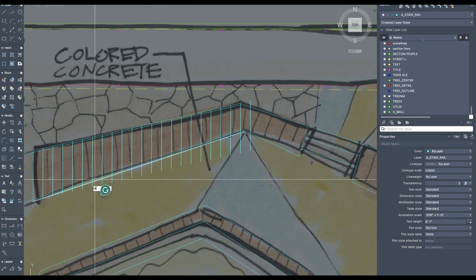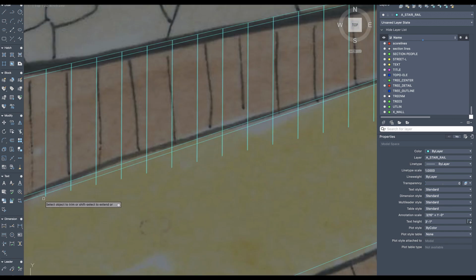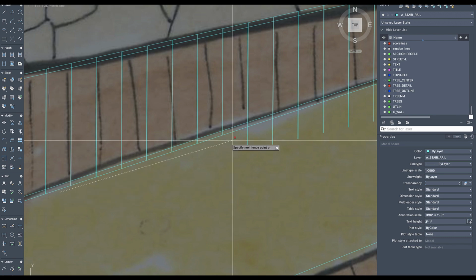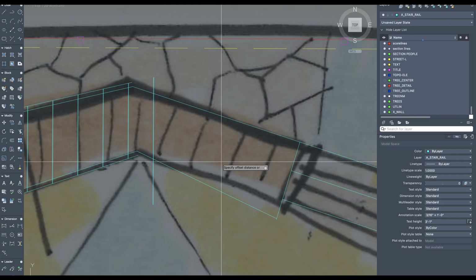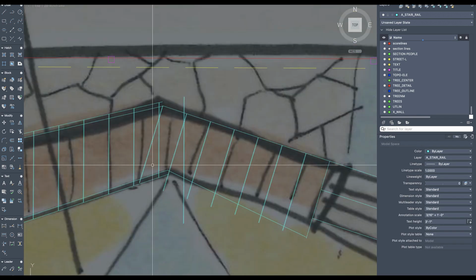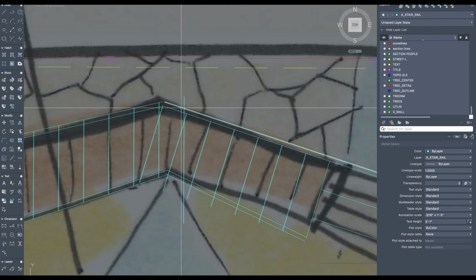We can use our trim tool. I'll say TR, and we're just going to grab these objects here, using that fence technique where we click and drag. All right, so this is going to be a fun little intersection here. Let's go ahead and set our 2-inch overhang on this stuff, this direction and this direction, and we're going to have to figure out how this whole piece fits together.